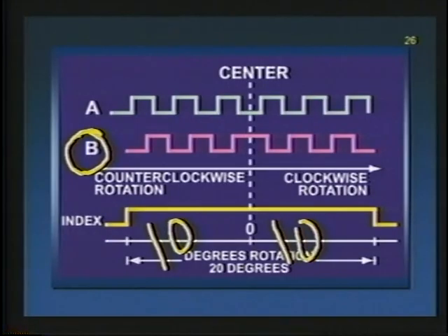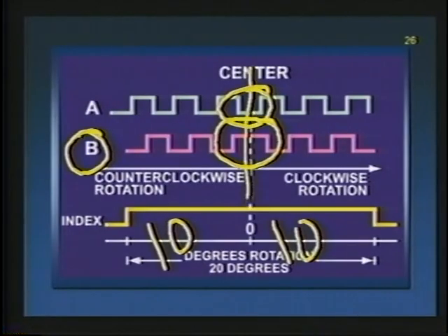Look at B: it's a square wave, but you can see twice the width there at the exact center point. That's another clue for the module, letting it know we're getting really, really close. And signal A should go to the low position. When all 3 of those happen, you are set up. Front wheels are straight ahead.